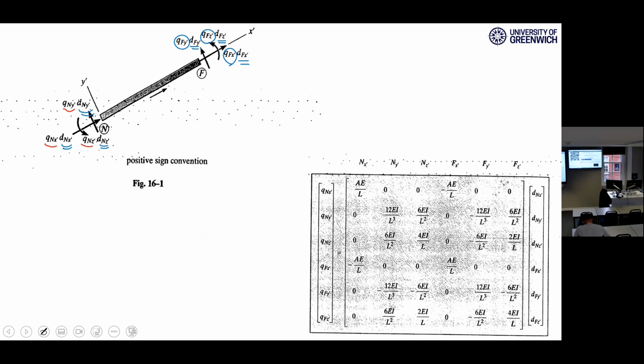And this is the stiffness matrix. What does it mean? Again, remember that it's a kind of F equal to K delta. Force, it's kind of relationship for a simple spring. You remember? Force is stiffness times deformation. This is the vector of forces. These three are forces at near end, and these three are forces at far end, aren't they?